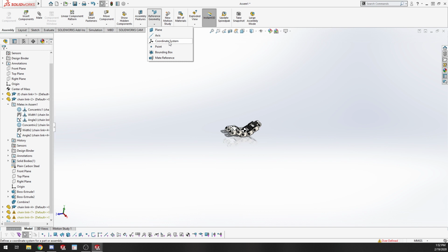For suspension, one of the coordinate systems we use is centered around the rear axle. If the chassis coordinate system is origin at the main roll hoop or something like that, I can add in that coordinate system, put the two rear wheels in, draw a line between them, make an axis, and then put a coordinate system right on the midpoint of that axis.